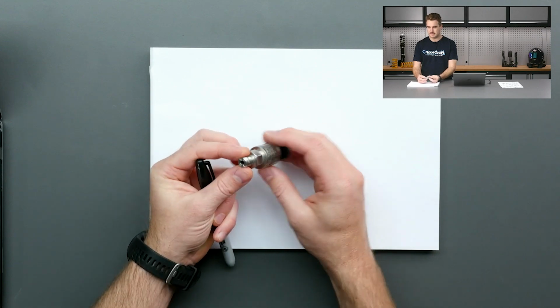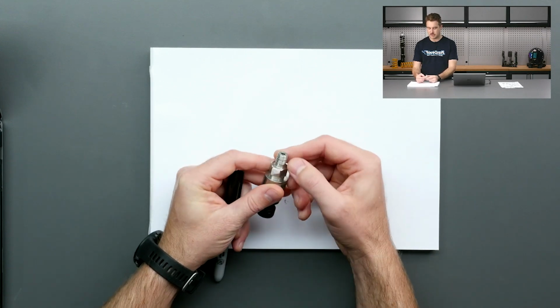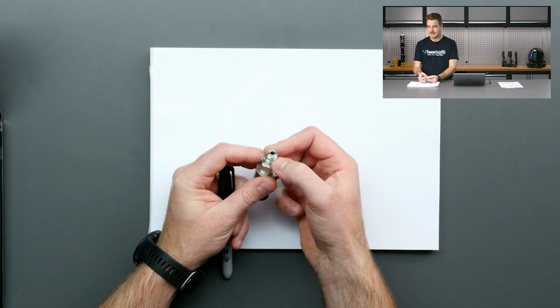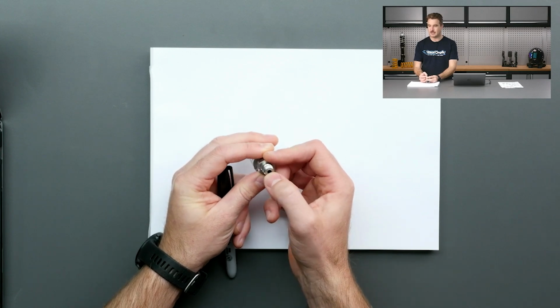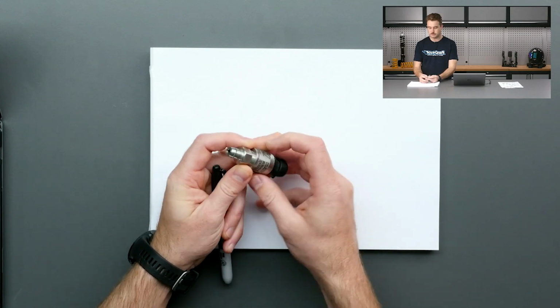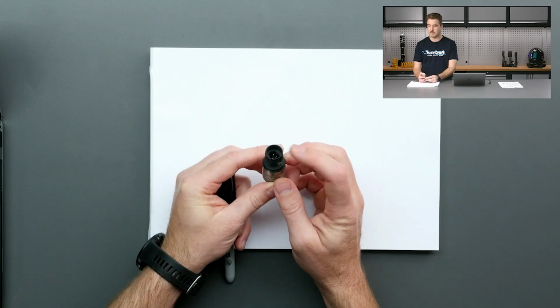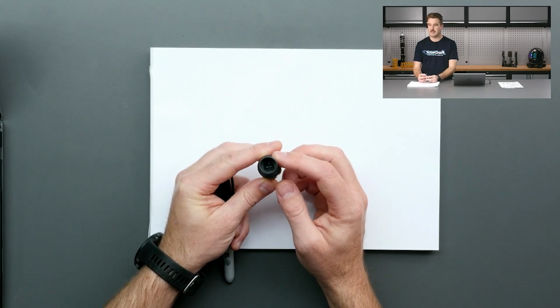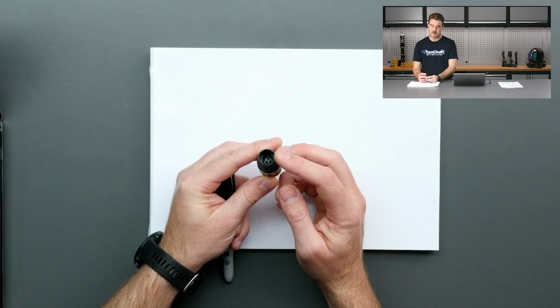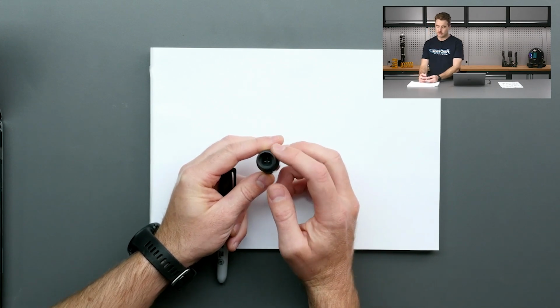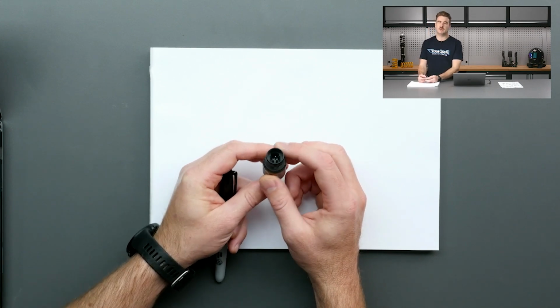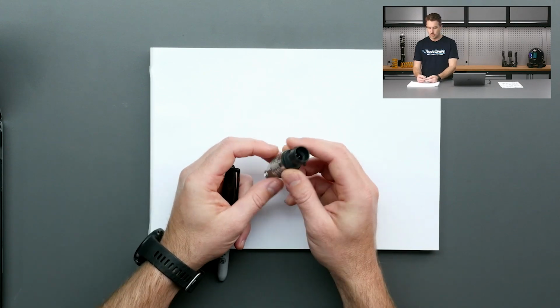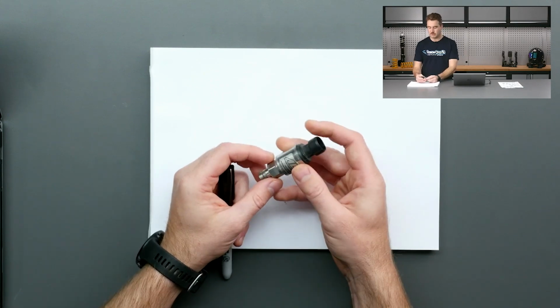What I mean by that is its layout is the same. This particular one has a tapered pipe thread on the end. It's got an inlet on the end to interface with the fluid. And then we've got a 3-pin plug on the back. So you're going to have a positive voltage and negative sensor ground, and one of those pins will be for the sensor output as well. Normally, most often these are a 0 to 5 volt style sensor.